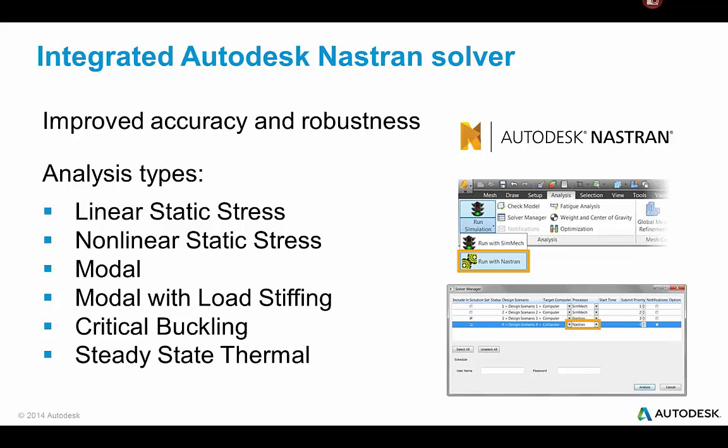You can do this one at a time for each design scenario using the Run Simulation button, or if you access the Solver Manager, and this was a new feature in 2015 to begin with, so if you haven't used it, I highly recommend you check this out. If you access the Solver Manager, you're going to get a new dialog that pops up and lists all the different design scenarios in your active simulation file.